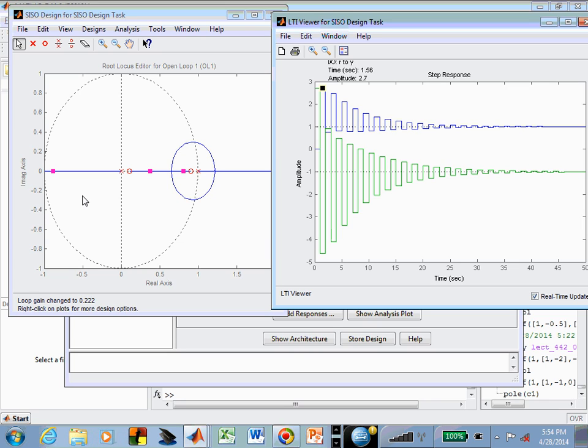Questions on this? Somebody, I think, asked, where did the z delta of 0.8 plus and minus j0.2 go? Well, I threw that away and said, I'm not going to worry about trying to hit a z delta. Let me just see if I can get a stable response.